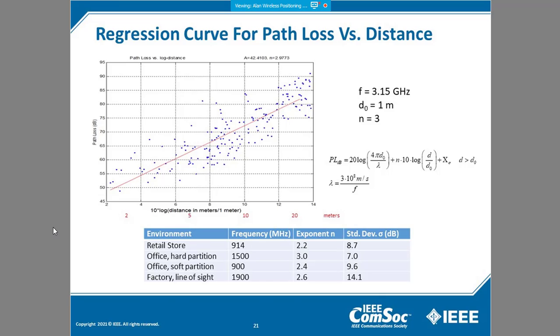So how accurate is the synchronization required? Absolute synchronization would be needed, or having atomic clocks, again depending on the accuracy determined, during the time period where the clocks are free running. It can be determined how different the clock times would be, and taking the difference in clock times, multiplying by the speed of light would give you an estimate of the type of accuracy that can be determined using that method. Okay.